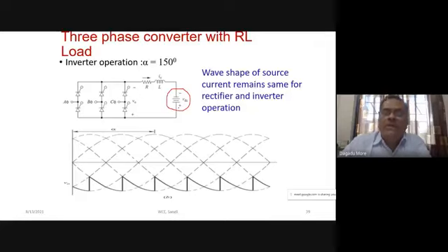We have shown the downward terminal is positive, and upward is negative. Whereas in converter rectifier mode, we have seen that upper is positive and lower is negative. But in inverter mode, the converter output polarity is lower positive, upper negative, because the polarities of the output voltage are reversed. So the first condition for inverter operation is that alpha should be greater than 90 degrees.